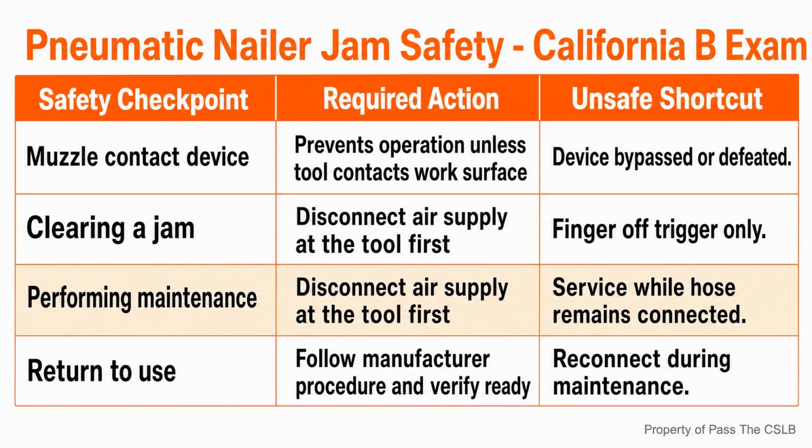Stop using the tool. Disconnect it at the coupling. Follow the manufacturer procedure for clearing or servicing it. Reconnect only after the tool is assembled, checked, and ready to return to use. Speed does not justify reaching into a connected nailer.